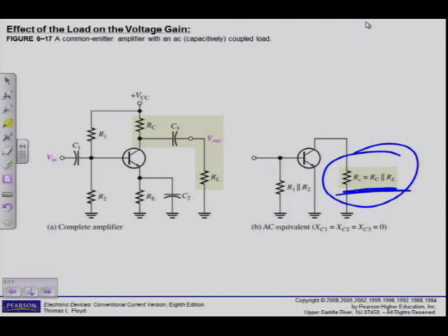Let's have a look. So now voltage gain, remember we said maximum voltage gain was equal to R, capital letter C, divided by R accent E, né? Then I also saw, okay, if I don't bypass, in that example it gave me a value of 152. If I don't bypass, then I have to include RE as well. Then it came down to, in this specific example, 1,76. All right.